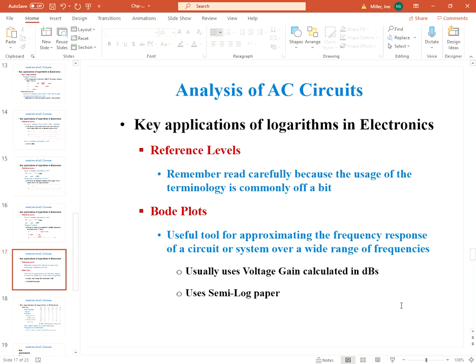33 dB. What is that power in watts? Or something similar where that's one of the stages of calculation. Obviously they left the M off in the reference because you can't find the power if it wasn't a reference to dBm like that.